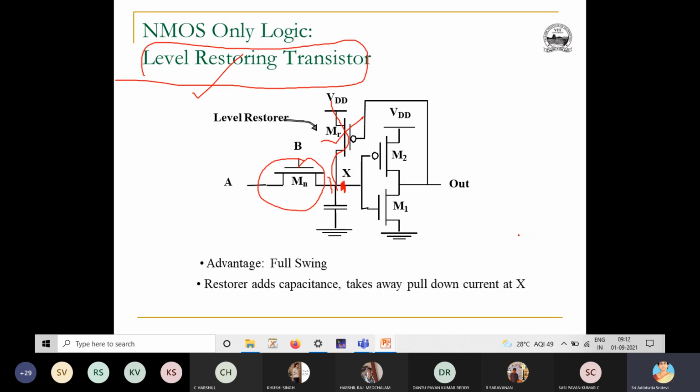If you implement that complicated logic using CMOS, you will get more transistors. So instead, we implement that complicated logic with pass gates, and only at the output of the pass transistor logic we can use a single level restoring transistor, when interfacing the pass transistor logic to the CMOS logic. Are you getting my point?